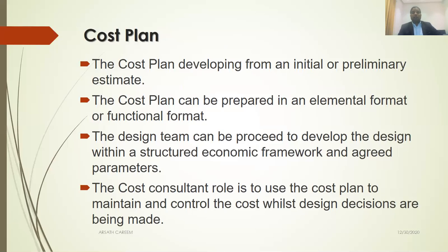You should know as a QS how to prepare a preliminary estimate. The cost plan can be prepared in elemental format or functional format. Usually, this is the standard as recommended by RICS.